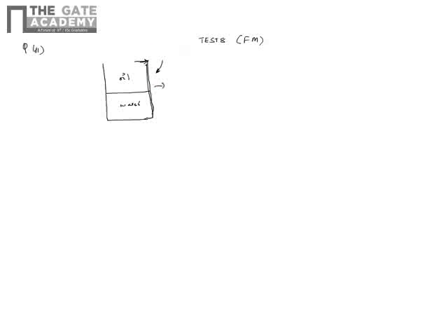So on this tank, let's draw the pressure diagram on this side of the wall. Starting here, it's 0, and as you know, when you have a fluid at rest and as you move deeper into the fluid, due to the weight of the fluid, the pressure increases with the depth. So this is 0, and as I come down till the half, it increases linearly as rho g h. Rho being the density of the fluid, this is the pressure here, and this is rho oil g h, h being this distance.